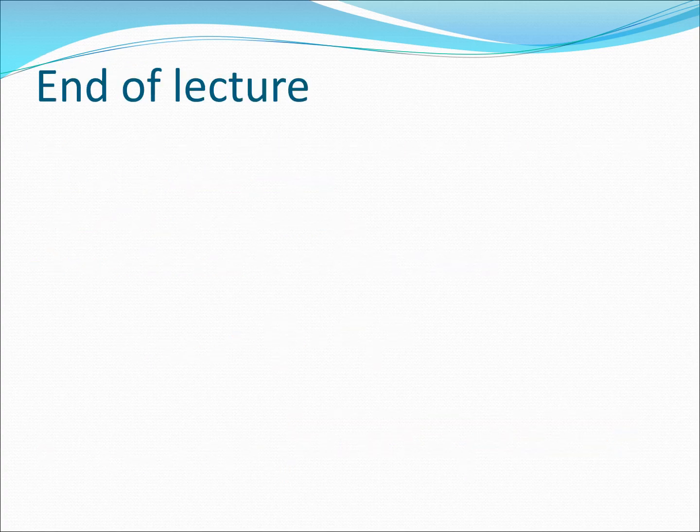Today's lecture is very important because it informs you that there are these various failure criteria out there, and this is one of the reasons why we spend so much time studying principal stresses. Very often when students are introduced to principal stress, especially in many books, they don't talk about it simply in terms of the eigenvalue of the matrix. They talk about various transformations and derive various cumbersome formulas, but you can actually do it in a simpler way by thinking of it in terms of matrices. But all this effort is because the failure criteria are expressed in terms of principal stresses.